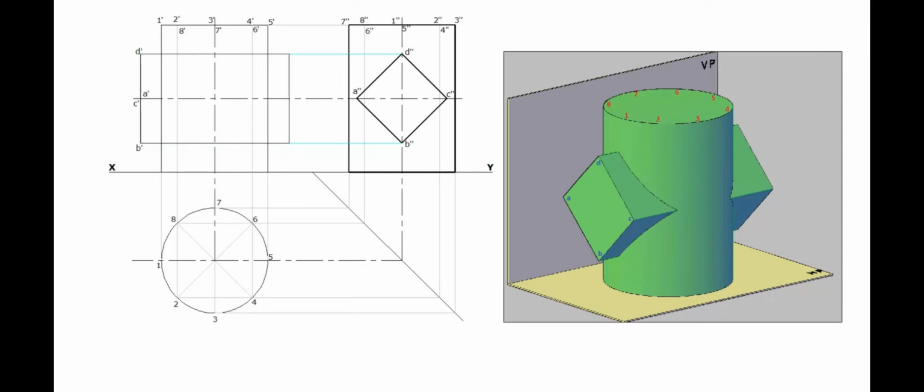Project the corners of the side view vertically till the miter line, then from there horizontally, to the plan of it. Complete the plan, by maintaining the same length, as that of the elevation. The longer edges of the plan are A, B, C, and D. In the plan, the edges of extended portion of the square prism are visible dark edges. Edges passing through the cylinder are invisible.